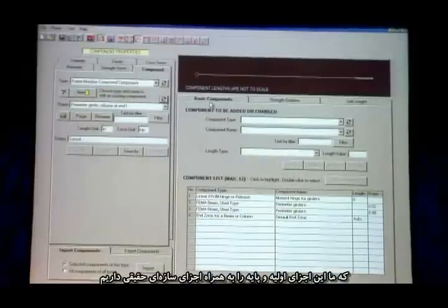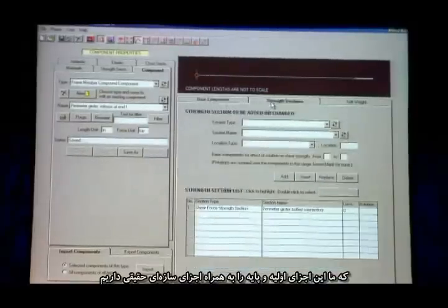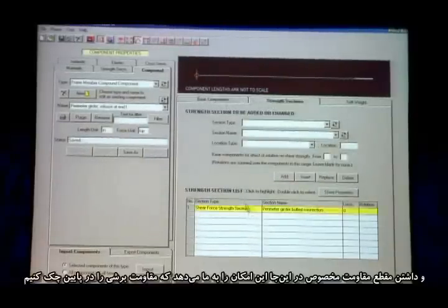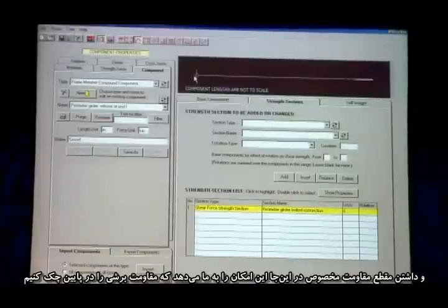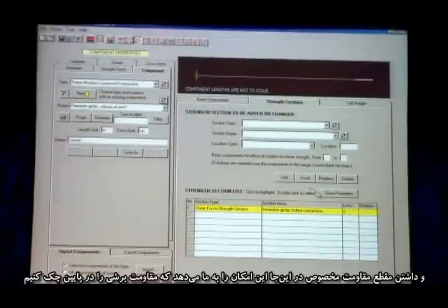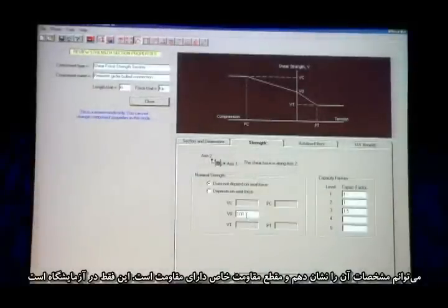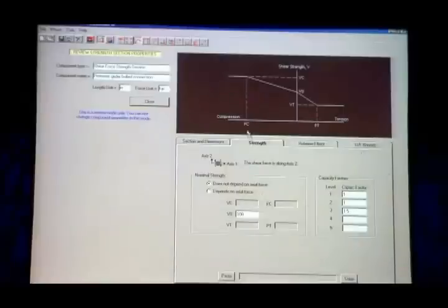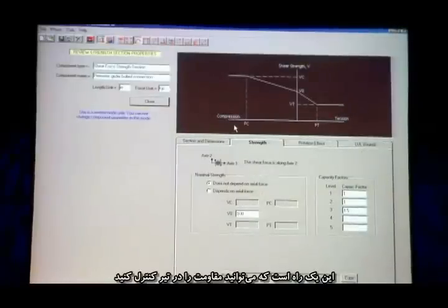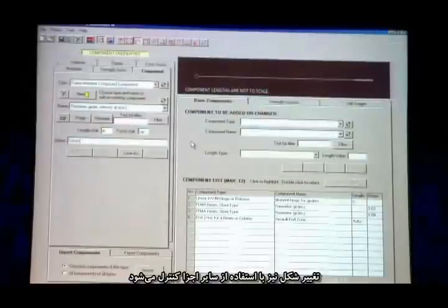And the way in which this is done is we have these basic components, which are the actual structural components, and then we have this particular strength section here, which enables us to check the shear strength at the bolts. And I can show the properties. And that particular strength section has got a strength of 100 kips. It's just a little arbitrary. So this is one way in a beam in which you can check the strength. The deformation would be checked using the other components.